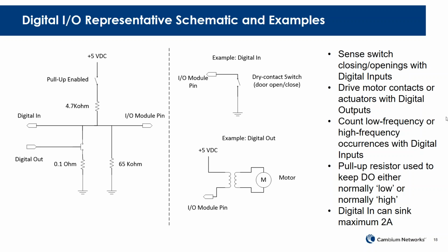So it's all readable through Modbus TCP. You can also turn on motors or turn on lights, for example, if you want to remotely control that all directly on the radio. And for that simple application, there's no need to have an RTU or PLC. You can do that directly from the radio.